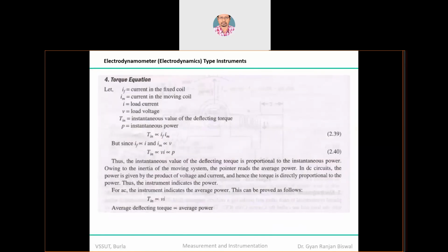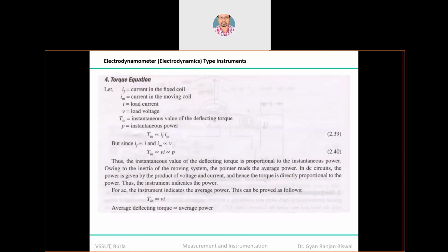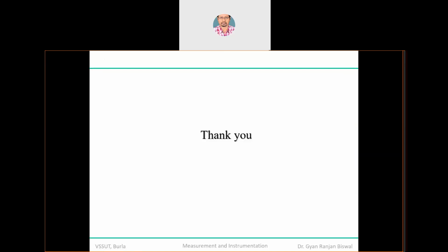Yes, this is what you have seen. I am trying to show you that RV is a non-inductive type of resistance with low temperature influence. In this demonstration the terminologies are a bit different. IF and IM are given, but it will ultimately give you the same result. How can you measure the actual power? As far as the wattmeter application is concerned, we will discuss it in detail next time.